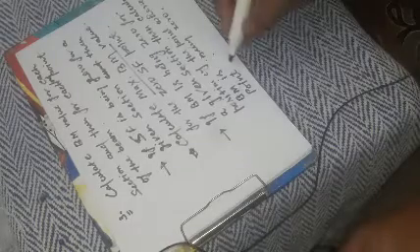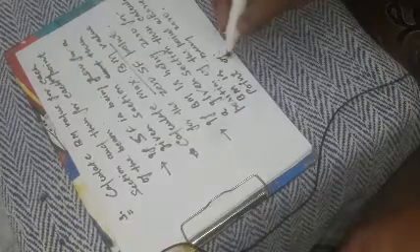So sometimes people also define it as the point at which bending moment curve changes its signs. So this point is known as point of contraflexion. So these 3 steps are required for drawing shear force diagram and bending moment diagram for the beam.